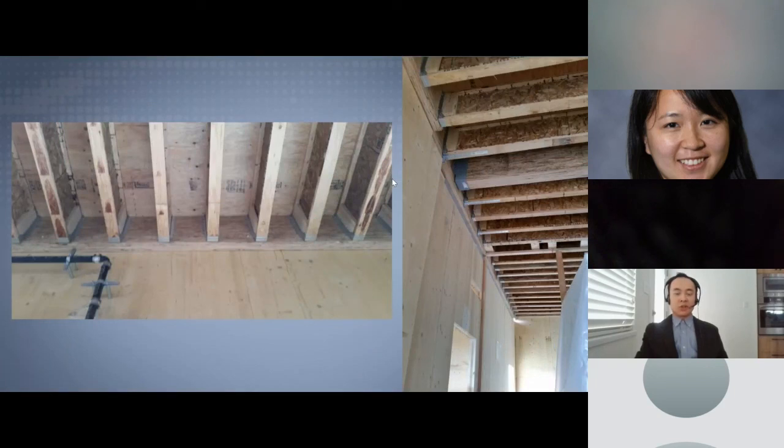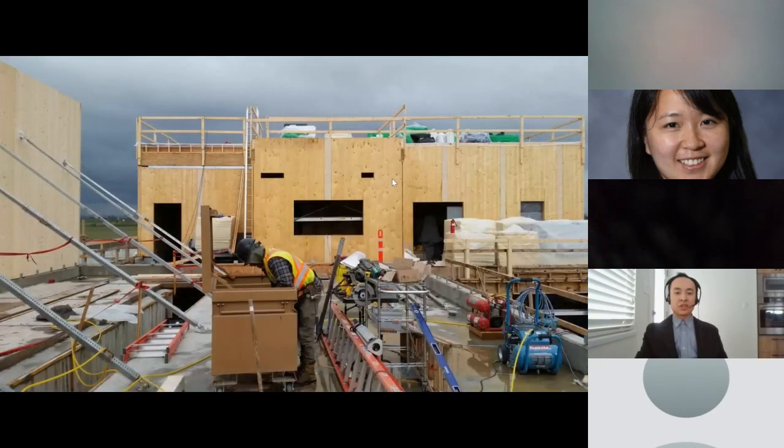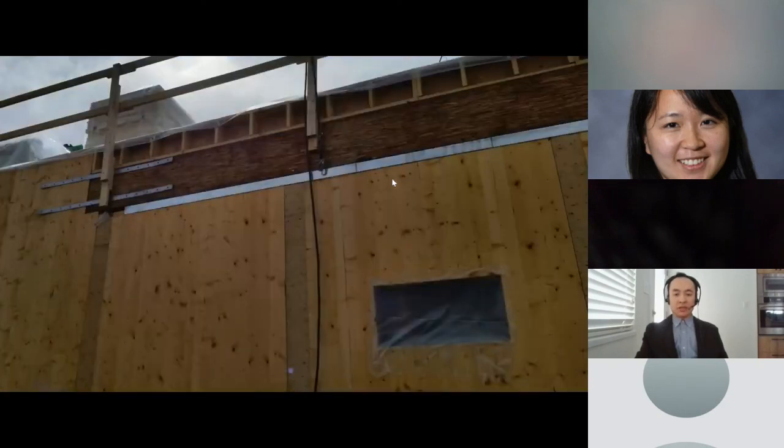These are the roof I-joists supported off of an LSL ledger that's screwed to the face of the CLT wall in the process building. This is the outside of the process building during construction. This is another photo taken from the outside of the process building showing the spline connections between the vertical seams of adjacent wall panels. You can also see a PSL beam that's acting as a drag strut that's taking drag forces into the rest of the shear wall via metal straps.